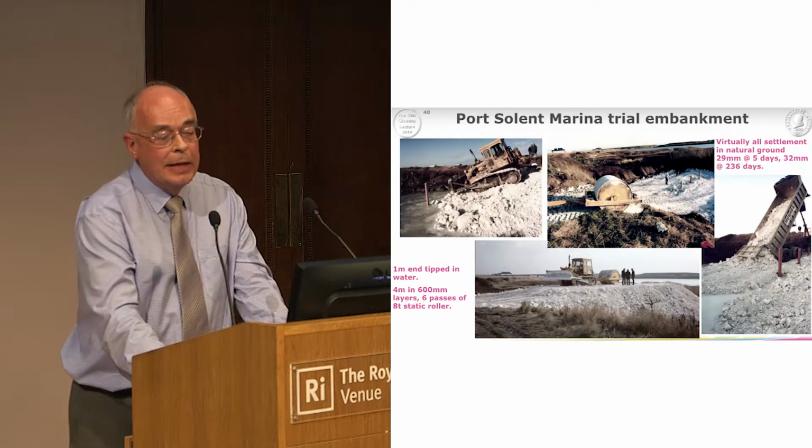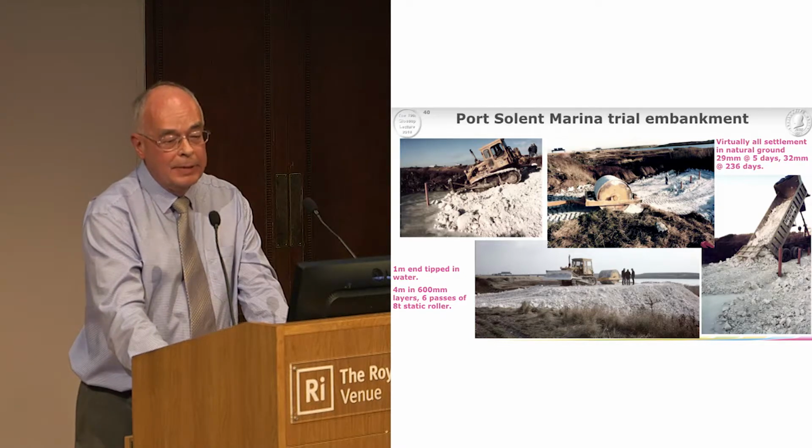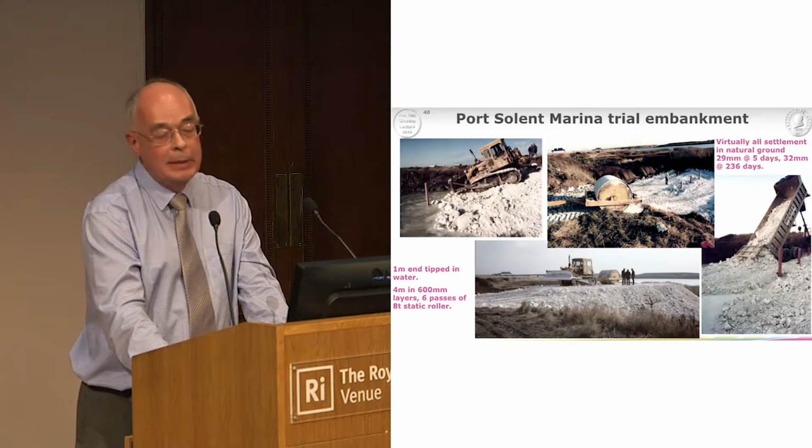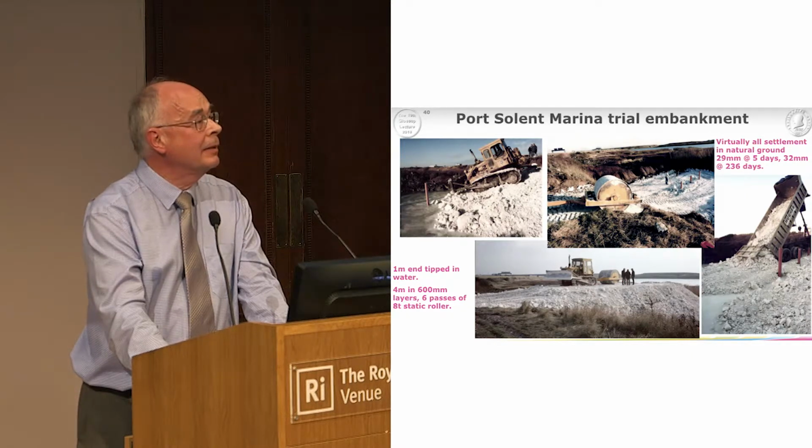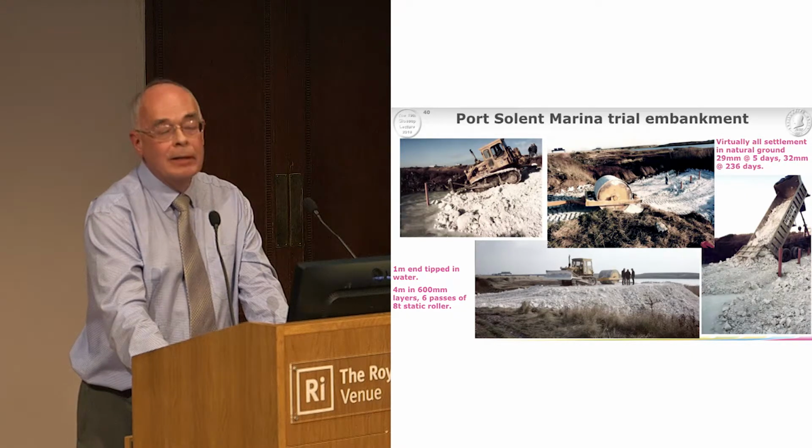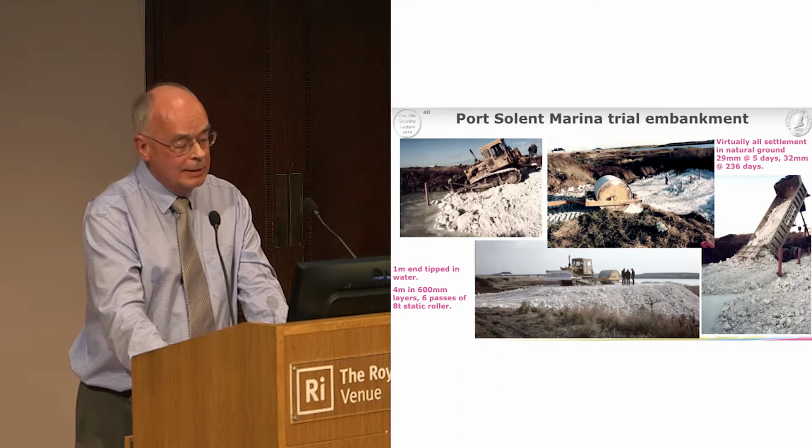And it turned out that virtually all the settlement was in the natural ground, and all of it was practically immediate. So we had 29 millimetres of settlement after the first 5 days, only 32 after 236 days.